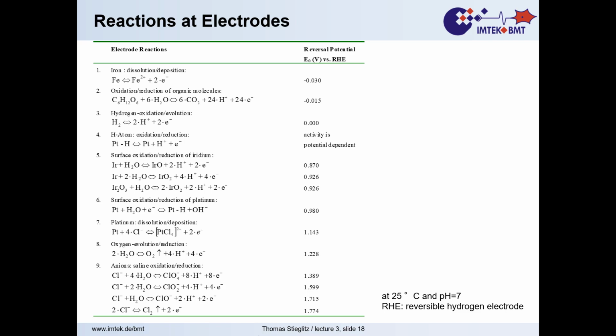So the first thing when you do developments is to find out where's my water window with that material. Either you know that material's water window, or you have a new material, then you measure that out, and then you take whatever, 20% or something like this, to stay away from the limits, and then you define that as your working range.